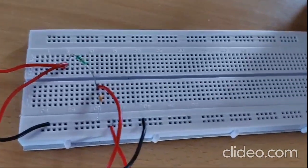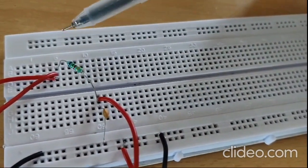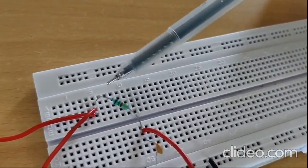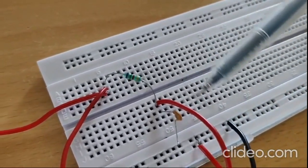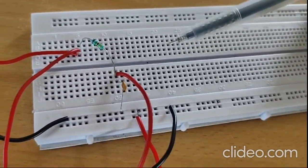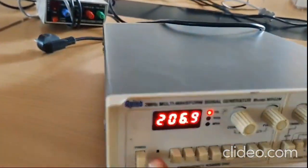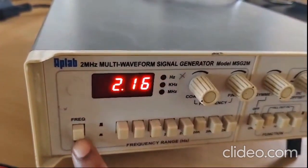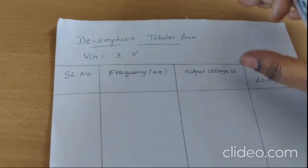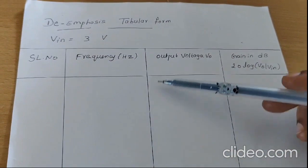Now we are going to see practically how de-emphasis is done. In de-emphasis, we have the 7.8K resistor connected the reverse way, and a capacitor connected like this, which is 0.01 microfarad. This is the circuit, and now we are going to observe the output. For the constant voltage of 3 volts, we are going to note down different readings for different frequencies.